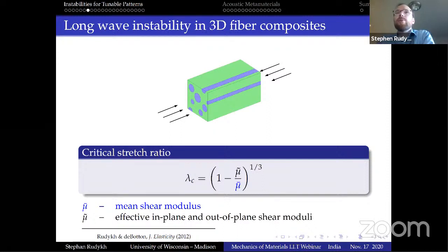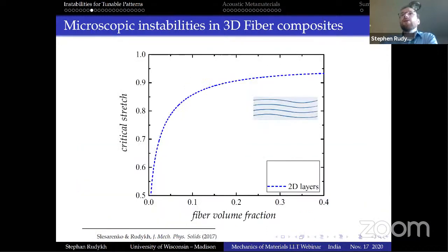Basically, we have the information here about the volume fraction of matrix and fibers and the properties of initial moduli of fiber or matrix. So this formula can be derived for weakly nonlinear materials, so when we have neo-Hookean matrix and fiber, but a similar formula can also be derived for materials with a stronger nonlinear behavior, such as Gent materials.